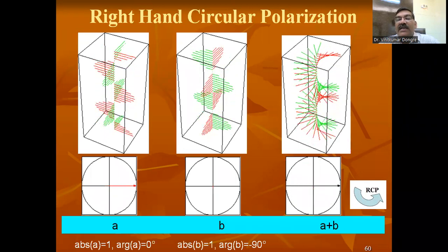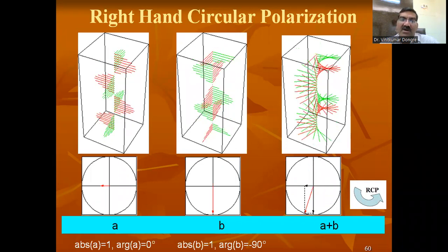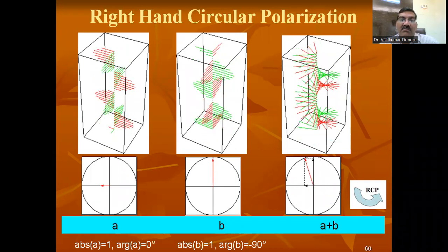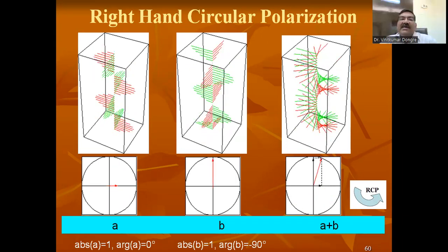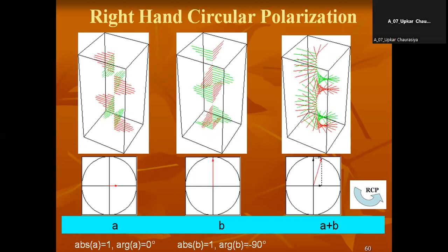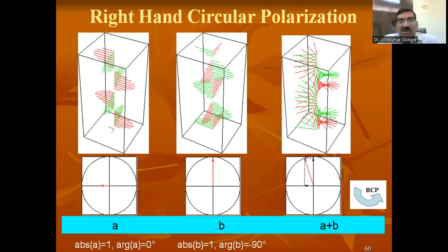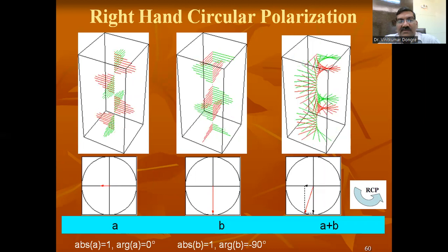Your dipole antenna gives the linear polarization. It cannot be designed for this. Yagi-Uda antennas are linear polarization. Yagi antenna is also not circular, it is also linear polarization. Linear, right? Okay. So got it. These are mainly the examples. The helical antenna gives circular polarization. Correct.